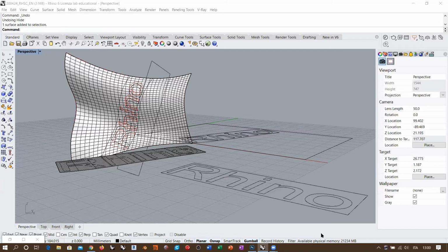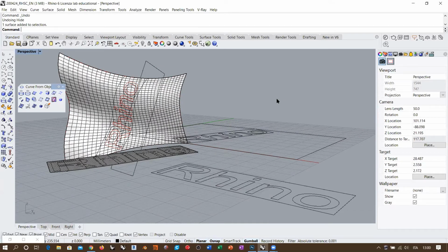I mean, what I understand from the long process is that, apart from how regular the surface is, which affects the results, the project command is lacking in precision compared to the UV way of projecting things. Well, more or less. More precise result. More or less. Yeah. The projection is a geometrical operation, while UV curves are a parametric operation. They both can lead to some deformation.